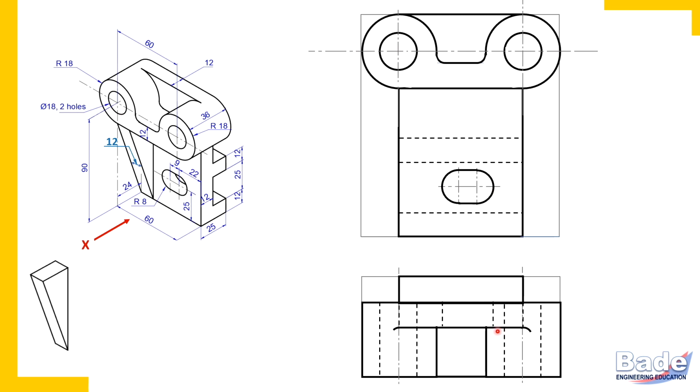One more part is remaining, that is this triangular plate. I have separated the triangular plate. Now its triangular largest surface, that is triangular portion, is visible in the side view. We are not asked to draw side view here, but in the front and in the top, since it is a plate, it will appear a thin strip showing its thickness. Thickness is 12 mm, which is parallel to length axis. So thickness 12 mm parallel to length to be measured here.